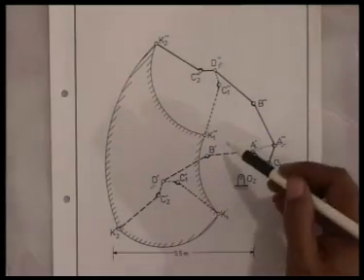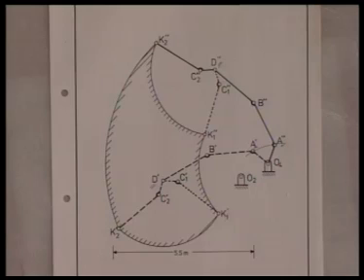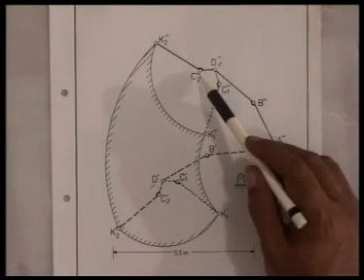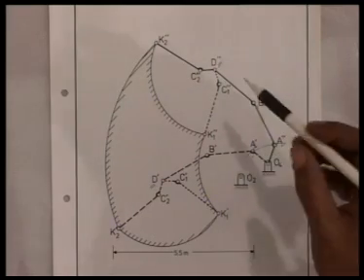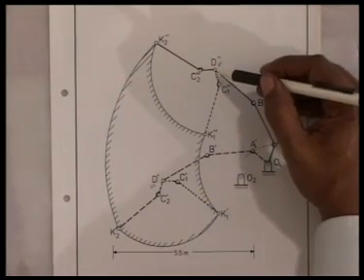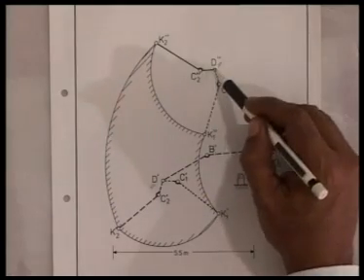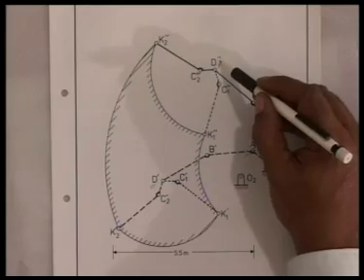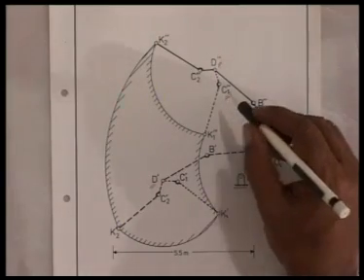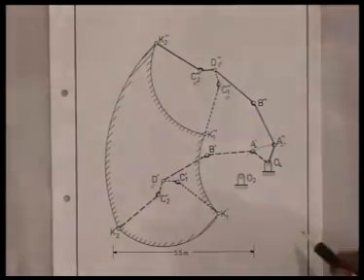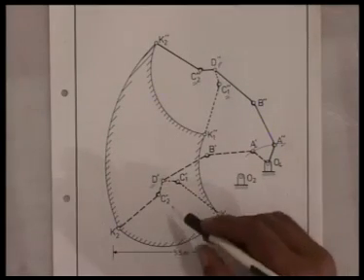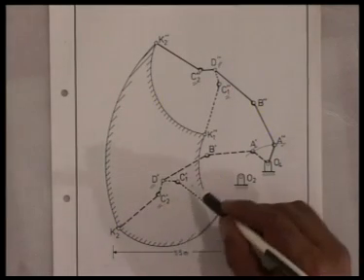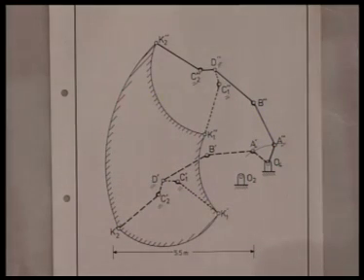For the extreme positions, one can see that link 4 and link 7 get rigidly connected and the distance DC also does not change. So, corresponding to the maximum position of DC and minimum position of DC, depending on the movement of the actuator Z2 corresponding to D2 prime, I get two locations for C. In the same way, corresponding to D prime, I get two locations of C, corresponding to the maximum and minimum distance of BC.